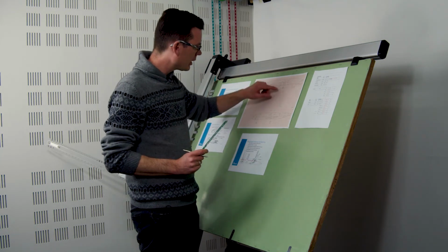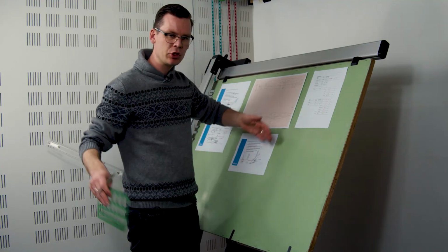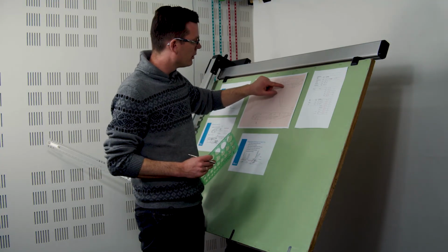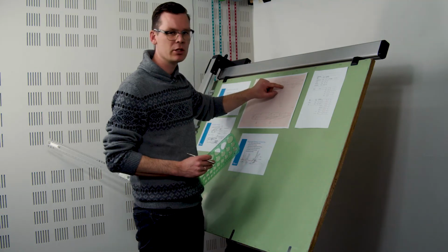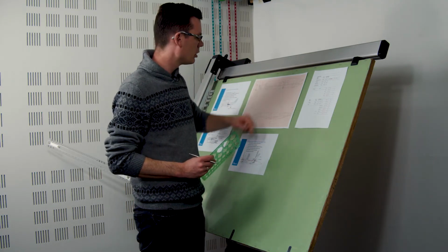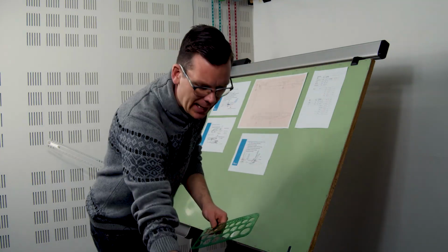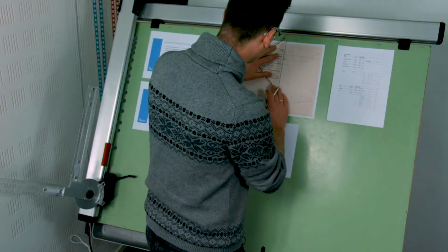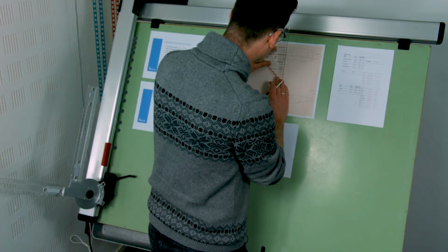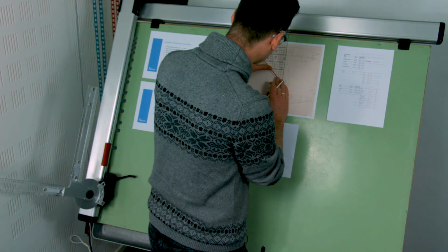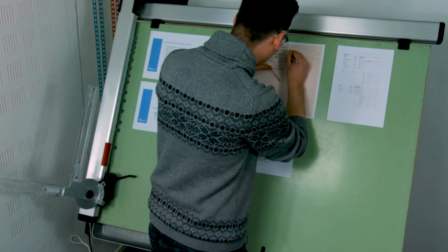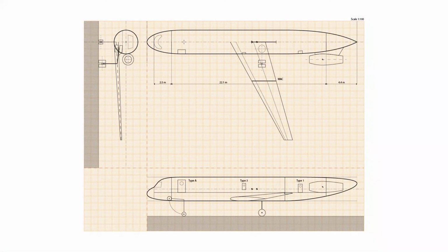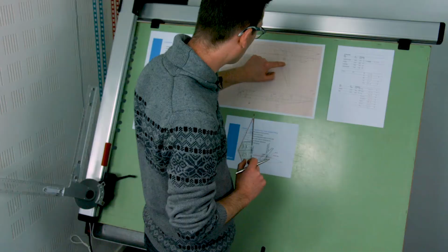The only problem is that when we are retracting the wheels here, that part of the wing is actually where the flap is located. So in practice, what we will do is add an auxiliary spar, as we call it, and the auxiliary spar is typically mounted perpendicular to the wing and intersects then the aft spar. So that's an auxiliary spar here between the side of body of the fuselage and the aft spar.